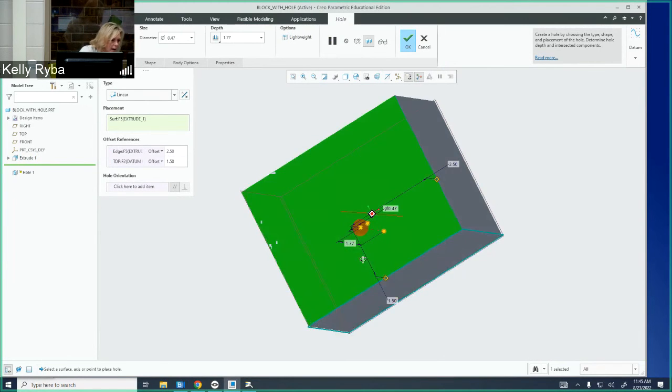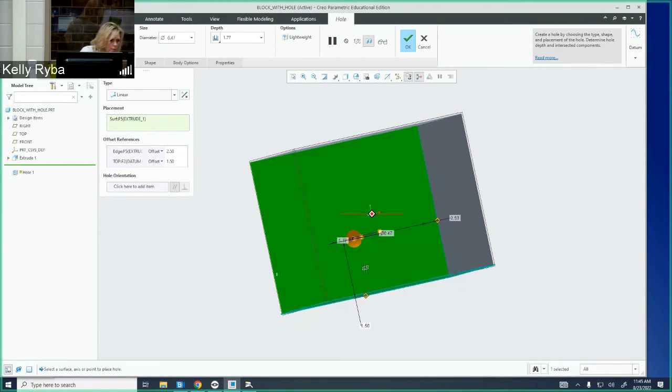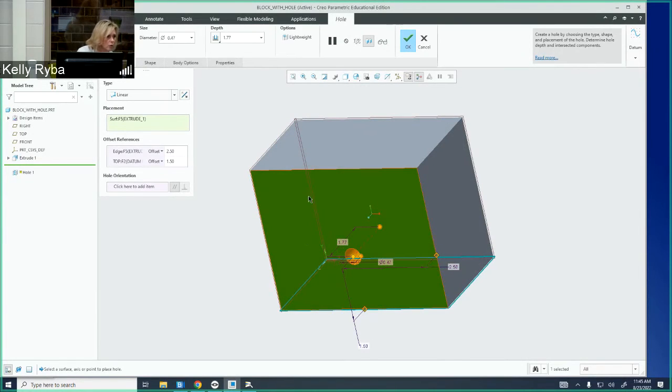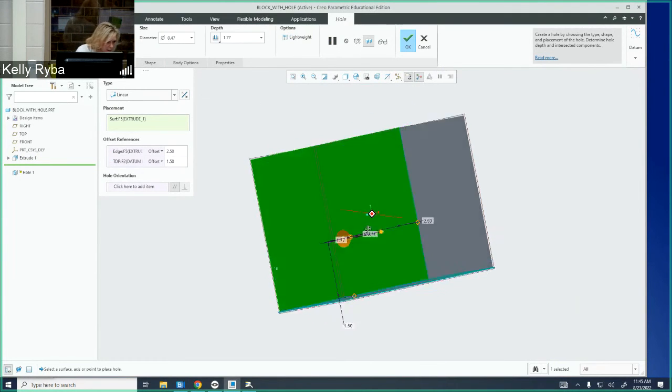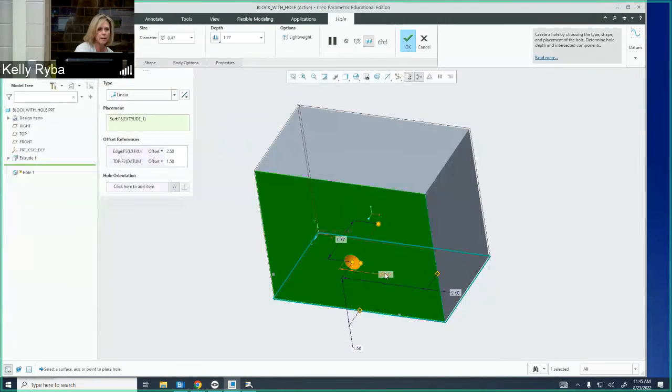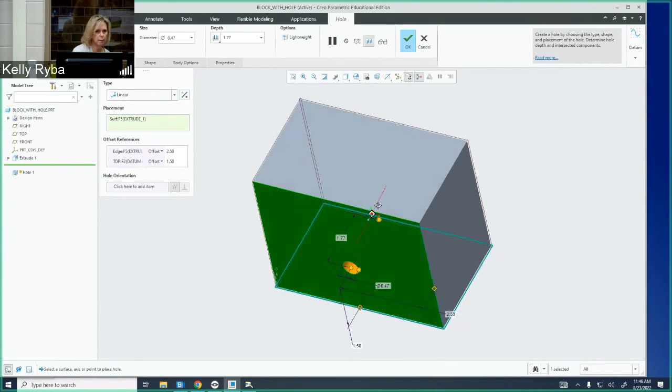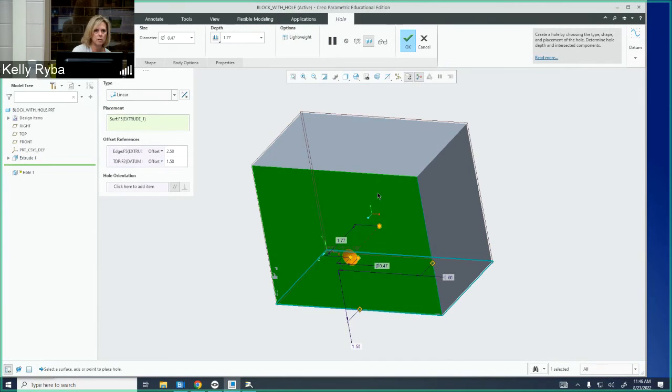All right, so now I need to set the size of my hole. Now, you'll notice that up here, I have the ability to put the diameter in directly, or you can also see that I have the diameter identified on my drawing here, right? You see that? And how I'm moving this around is I'm taking that middle roller, I'm depressing it, and I'm just moving my cursor. This is just like SolidWorks, actually. I'm going to double click on that, and we want this hole to be 1 inch. So I'm going to put 1 and then enter.